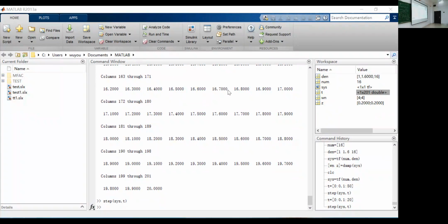0.306 seconds, right? And how about steady state? Steady state means the whole system response enters a relatively stable situation. So maybe it happens when time tends to infinity. So the final value shown here is what? So this whole system responds to a unit step, the output curve is shown here, and Matlab can read all the parameters you need for you. So no need to read the figure, and it gets more accurate results for you.